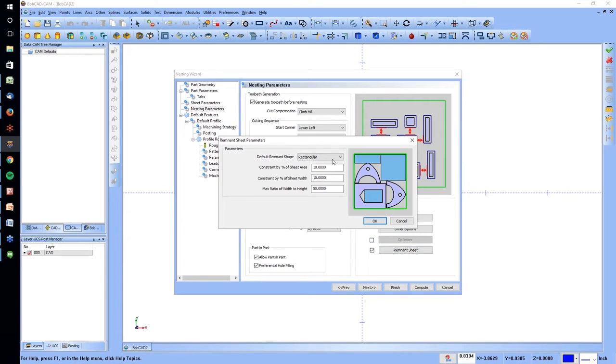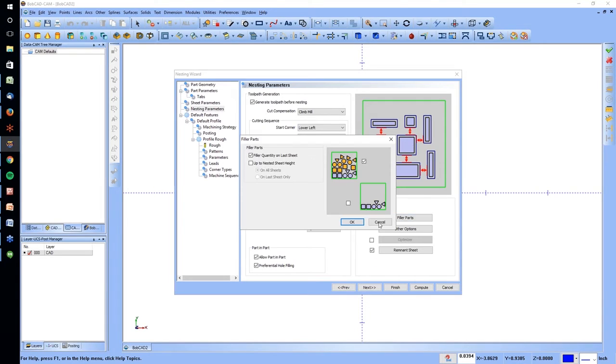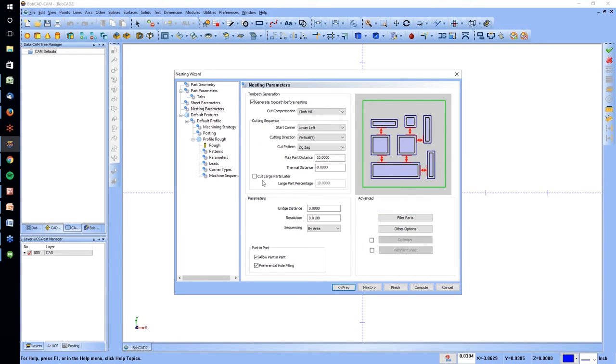And then you guys can choose rectangular style, true shape, stepped, or kind of steps away, gives you rectangles. And then you also have clean cut, where it just cuts it clean. And even though there's open areas here, it would still be open. You get one clean, nice cut. Okay. So those are the remnant options as well. We're not going to worry about that right now. We're going to just do a normal nest.